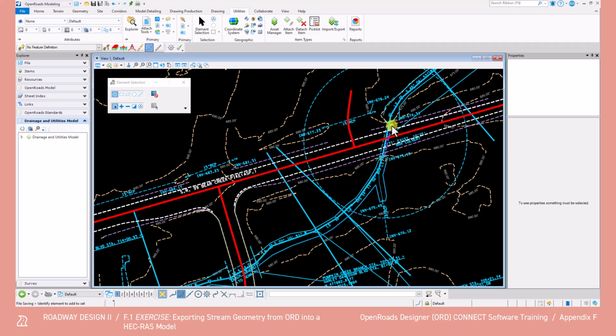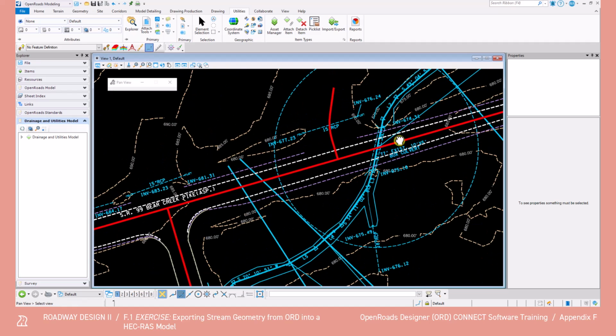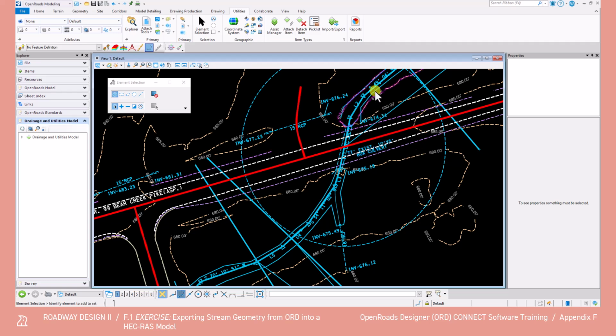The survey reference file provides maps, survey elements for the project area, including the stream center line for Pumpkin Creek branch, the bank extents, end walls, and the pipe culvert invert elevations. So we've got the stream center line and then the bank extents. Now let's review the survey data along the stream and locate the existing 77-foot long 10-foot by 5-foot box culvert within the dashed blue circle.